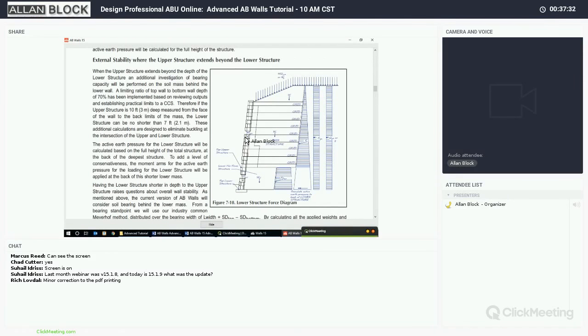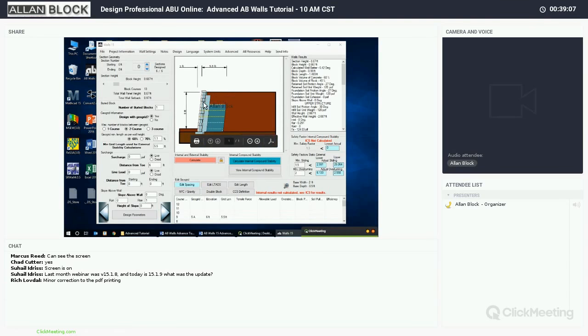And so the software is pretty good about this. When you look at the complex composite structures, one way to enter this real easy is by simply removing GeoGrid. If I go to Edit Spacing here, which is highlighted, and click on the layer of coursing that has grid, it simply removes it. But now all of a sudden, I've got 4 courses that are unreinforced.